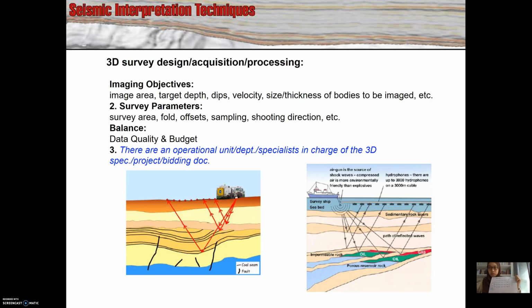When the boat tows throughout the sea, it will go something like this. The boat will move in this direction, and then it will make a hook or a loop. The loop they are making is the point where they correlate the data to become a cross line. Actually, we did not really acquire the data for the cross line, but we use a processing technique to correlate the data at the same particular point at the receiver, and then we combine it to become a cross line.